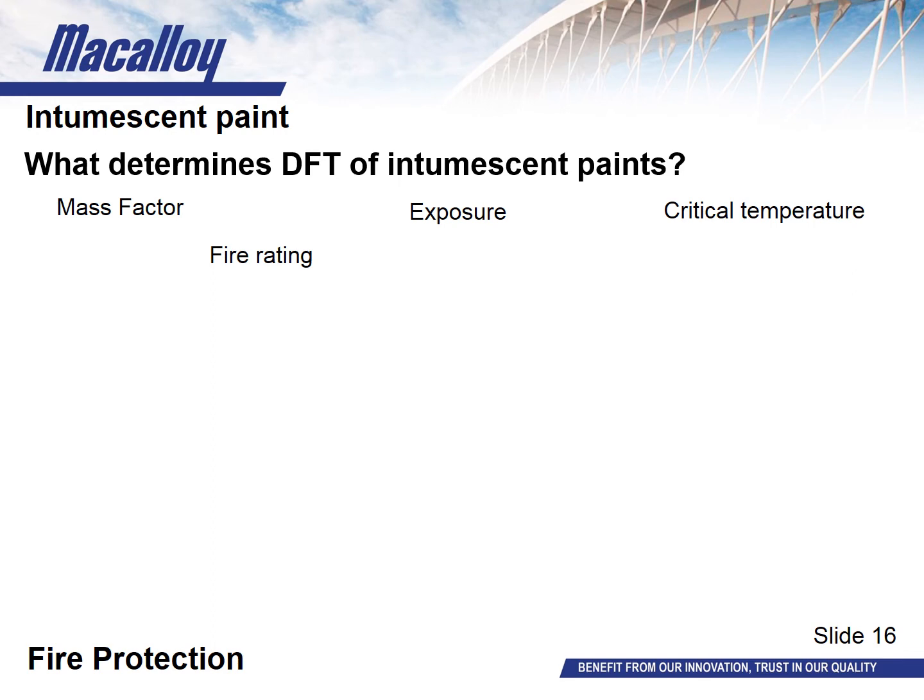So in the UK, Approved Document B outlines minimum requirements for fire resistance depending on which floor and type of building you're relating to. So obviously when you're selecting your fire protective system, it's important to know what test standards and approvals the system has been tested to, as different thicknesses for different systems can offer the same protection, so it's always good to do your research beforehand.